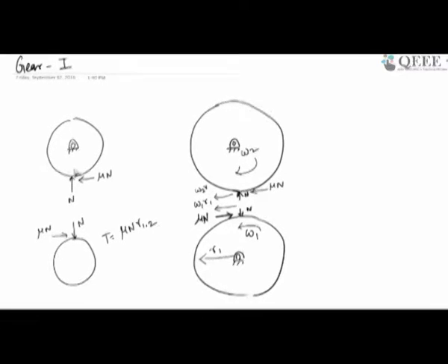But now if the disc has to be in equilibrium, it has to get a force n from the shaft, which means the shaft has to get back the same force n, which essentially means that the shaft which is holding this disc will be subjected to a transverse force n.